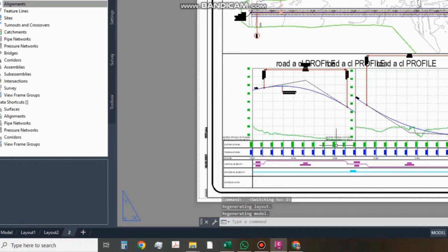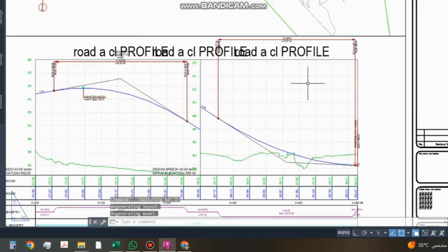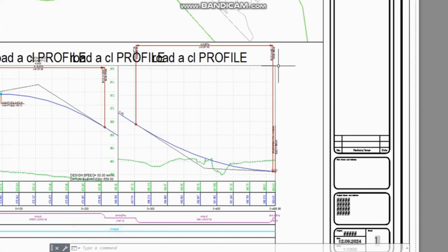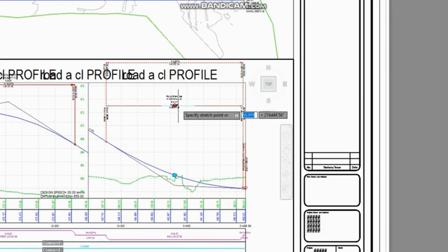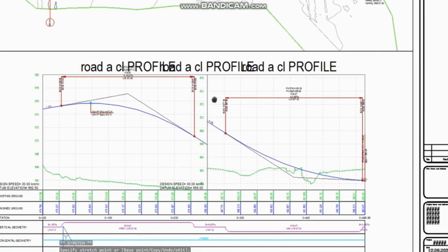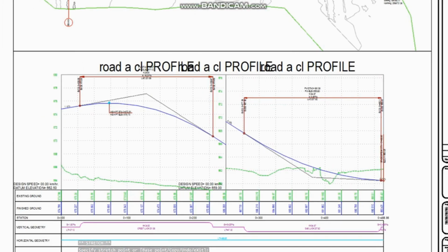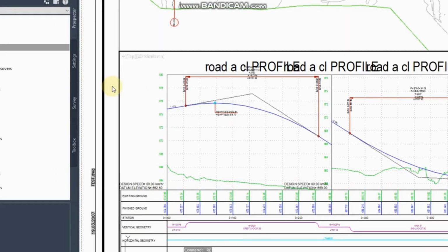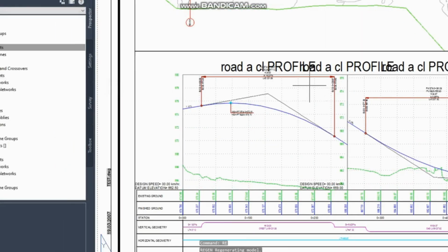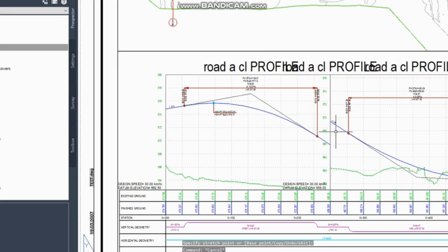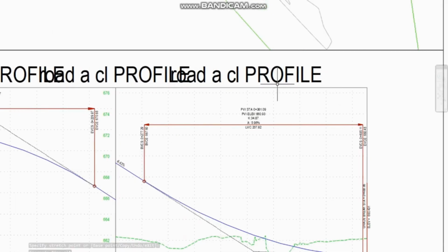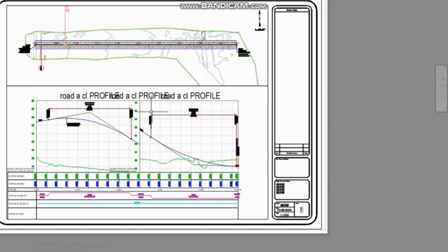You can adjust now. You can see how it looks, because this is Civil 3D, so it happens like this. So you can go inside here and manually adjust this curve data sometimes if it is needed. I will also adjust the second curve. So like this you can adjust your profile. If it has high and low elevation, you can divide it into the split profile.